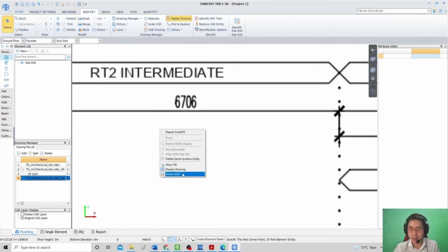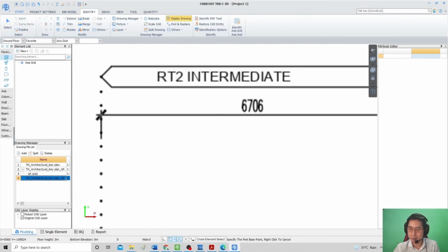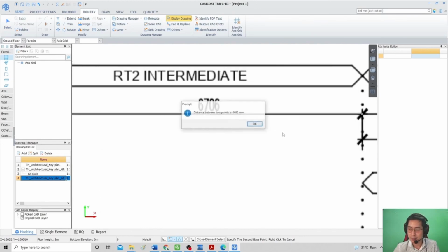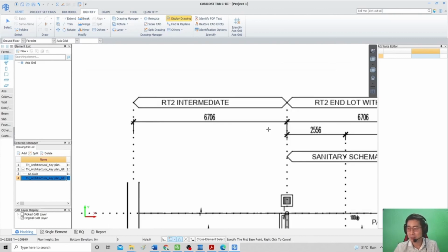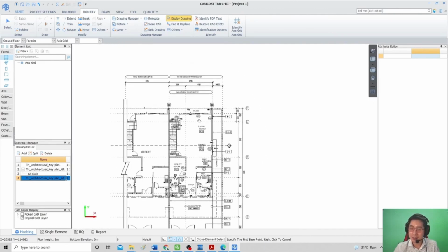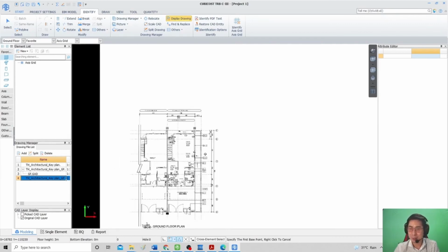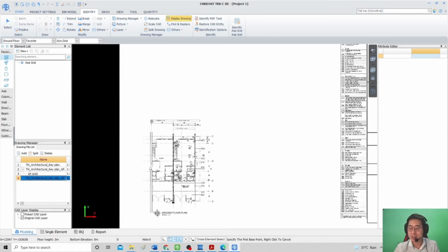To cross check this, press on distance, select the random point, select the first point and the second point. From here you can see 667. No matter how many times you skew on the picture, somehow it won't be 100% accurate, but at least we can get closer, because it's a picture form. You have this kind of problem. Yeah, so that's why try not to get the scan copy in picture, JPEG or BMP, because it will make your modeling process quite hard.